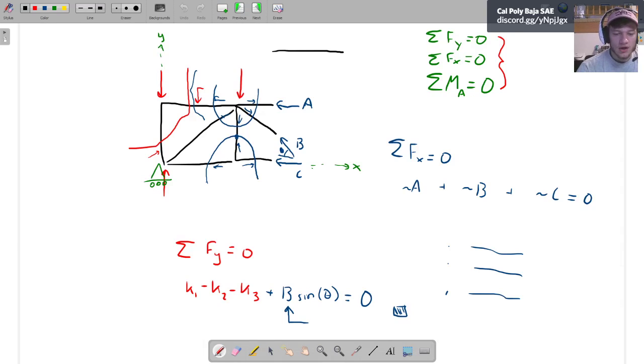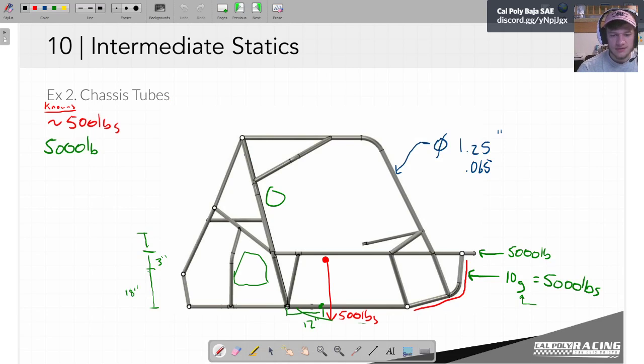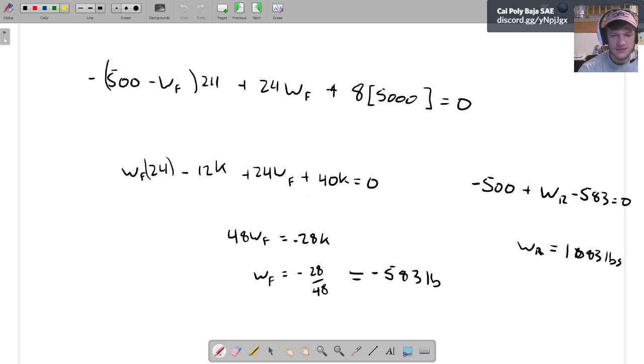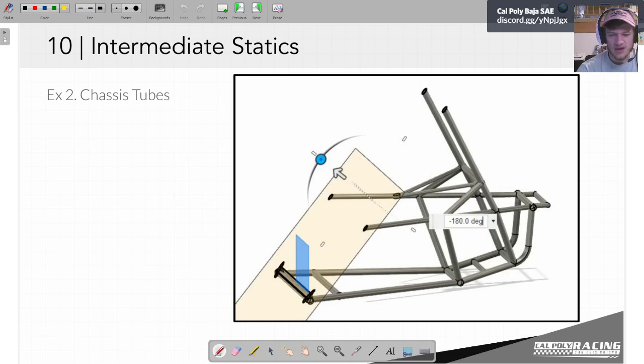So hopefully we've mitigated that by now, and now that we know the forces being applied at these 3 locations, we can start to figure out what's going on in this member here. Remember, at the beginning, that was the whole idea. The whole question is, how does this member look? And I'm sure you can see where I was going, or if you saw the spoilers, we're going to make a cut right along those members.